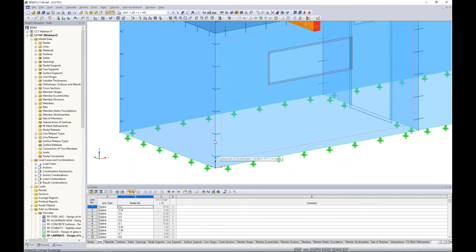When I zoom in here to the line hinge location of these two panels, what I see is hinges on both sides. Now, with any finite element software, whether it's RFEM or anything else, we know that if we have two beam members framing in at a joint, and those are the only two beam members that exist, and we set the end rotation of these beams to be released for moment, we're going to get an instability. You never want to set both beams in that case to pin. You want to leave at least one fully fixed. Otherwise, we get instabilities and we can have issues within the program.